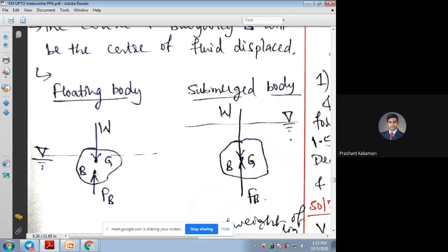Now if you see, the weight of the given solid body may be concentrated at this point, the volume center of the stone, for example. Now, to find the location of the buoyancy point, I'm taking the volume of liquid replaced. Here, liquid is partly just below the surface of the stone. Whatever the volume is, it is in 3D, not in 2D. If you consider this three-dimensional volume of water replaced, the center of that liquid volume itself is the buoyancy point.